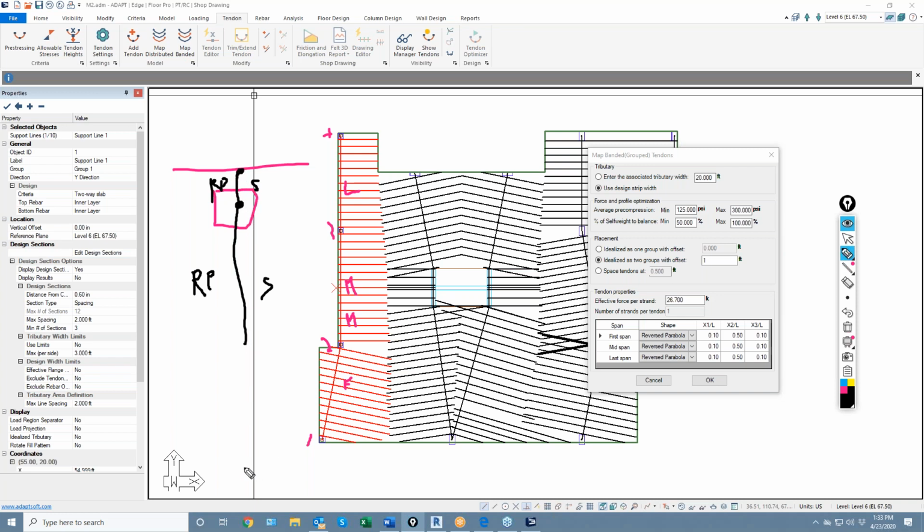Really, the cable, if I flatten out the drawing of it, the cable here might be low, and then it would just exit out of the slab at the CG here. So you'll have to go back and edit that after you've mapped. That's something that's pretty common if you're creating those 2 points, which in the past was a legitimate requirement if you didn't want to add a bunch of splitters to generate the design tributaries. So keep that in mind.